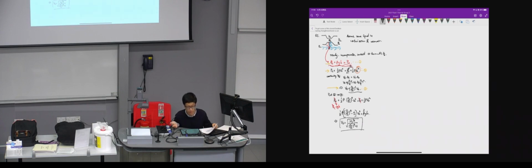Otherwise, if it goes to the venturi section, you can no longer use Bernoulli because you change the mass flow by input as something else. So it says draw the fluid upwards but not into the reservoir. It also double checks this by saying which is just sufficient to cause the reservoir fluid to rise in the tube up to section 1. So you can still apply the continuity equation in this problem. This is a bit confusing.